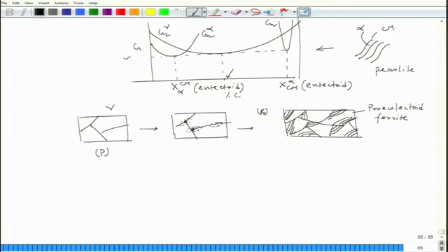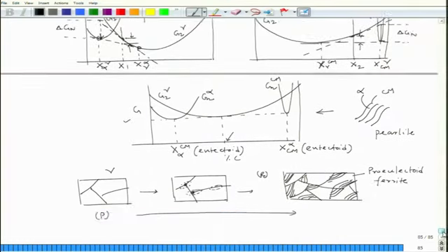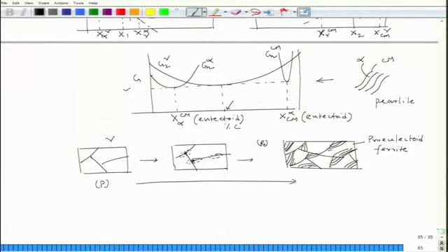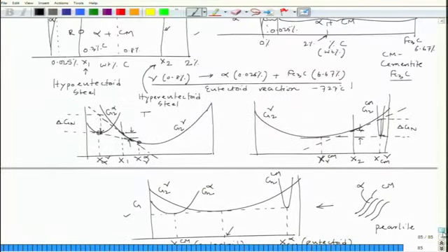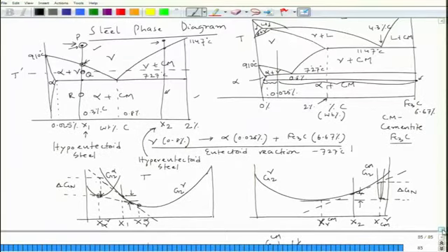So, that means starting from gamma I would get to this microstructure, and if I try to see what will be the pro-eutectoid ferrite content, I can easily find out from the tie line. Let us say I draw a tie line here just below eutectoid temperature, then I could understand this is my pearlite region, this is my pearlite.